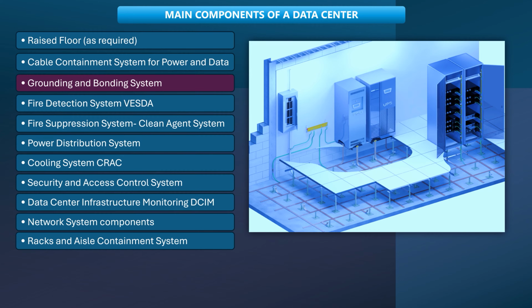Grounding and bonding are important in data centers to ensure safety and reduce network problems and equipment failures. The goals of grounding and bonding are to minimize current flow and to carry noise induced by electromagnetic interference to ground. All metallic components in the data center should be bonded to the grounding system to minimize current flow and to send harmful currents away from the equipment.